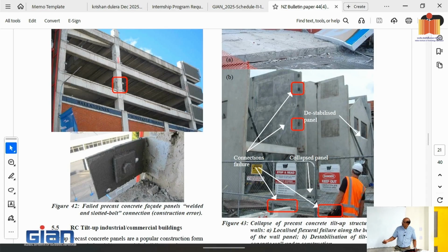Typically, to create pin details, they would use rebar connections or bolted connections. They typically use that for the bottom of columns to mimic a pin connection, as well as beam to column. When you concentrate them, especially if you put in multiple threaded rods, people assume they will all act simultaneously, and that will not be the case. When that happens, pull-out elongation will happen. If it goes back and forth in cycles, then it becomes a sliding problem. So the elongation of anchor rods was a very common thing.